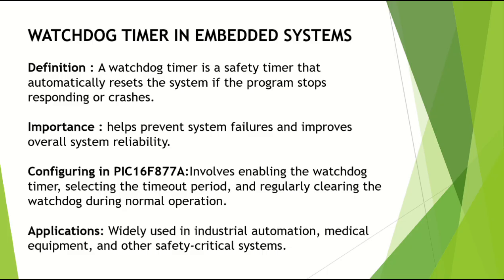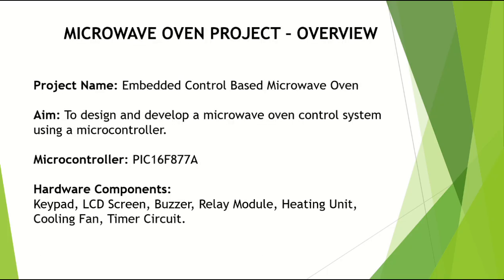Now we are talking about our project in embedded systems, that is a microwave oven. The project name: Embedded control-based microwave. The aim is to design and develop a microwave control system using a microcontroller. The microcontroller is PIC16F877A, and we use hardware components that are keypad, LCD screen, buzzer, relay module, heating unit, cooling fan, and timer circuit.